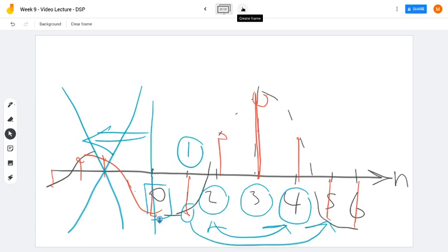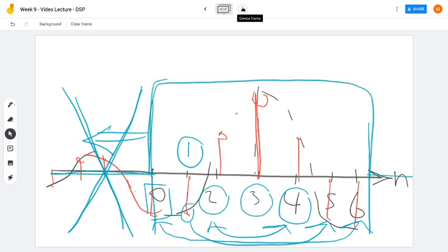So I will keep the samples up to 6. If I take the sample at n equal to 7, I will not have a symmetrical sample on the other side. It was at n equal to -1. But I have already got rid of this negative part. So I will only keep the impulse response from 0 up to 6, and ignore all the samples before and after, outside of this window.